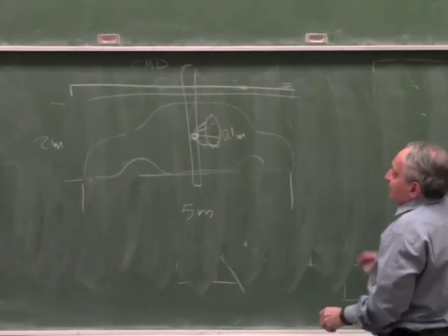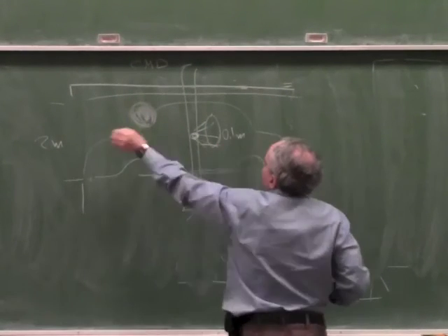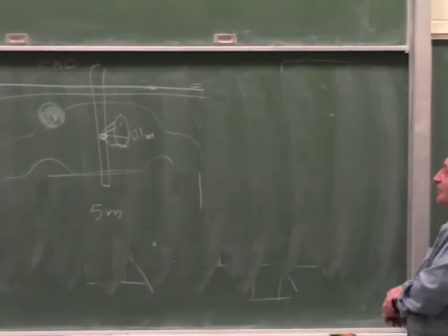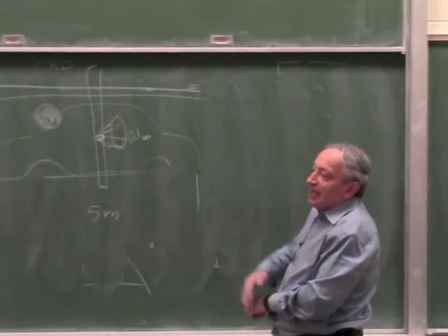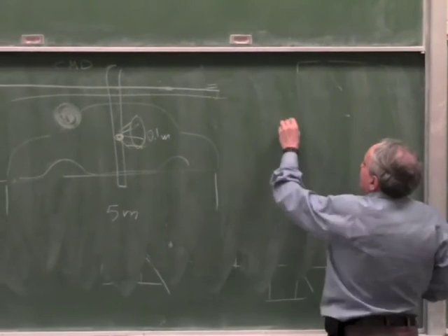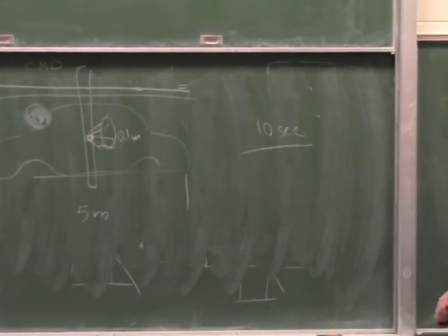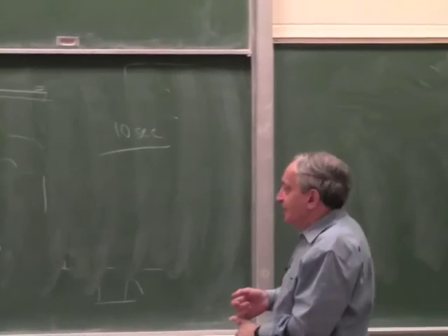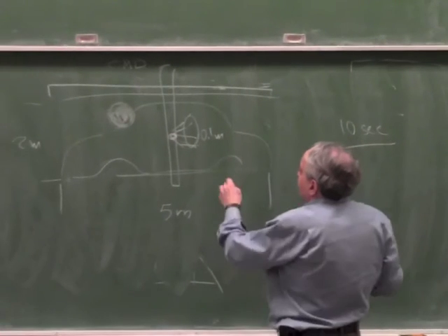So the way I paint the car, I have a circle of paint, and I just move it like this. And let's say the time to paint this side of the car is 10 seconds. So what I want to know is, for the system, which bandwidth do I need of the actuators? We can talk about accuracy, although here, let's say, accuracy is 1 centimeter.